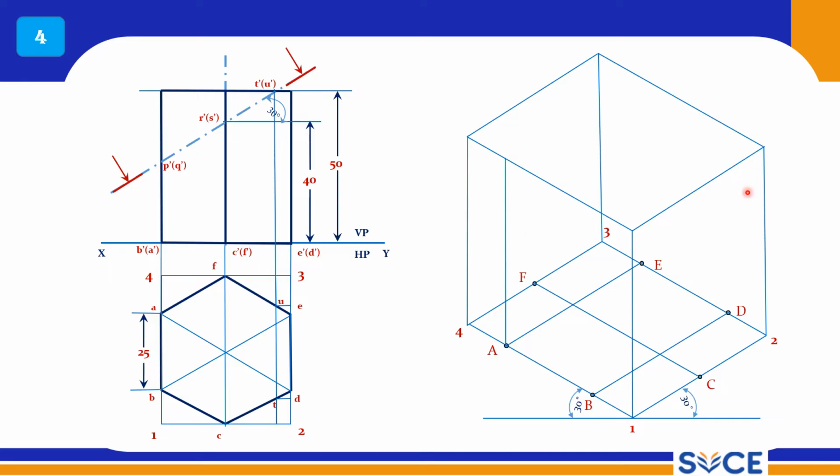Up to here the procedure is normal, and now you have to measure each and every cutting point and mark them. So you have P. P is on BH. Q is also at the same distance, on AH. On AH you have Q, point Q. On BH you have point P. On the C edge, so this is the C edge, on C you have point R. So measure this vertical distance and mark it on this C line. That gives you R.